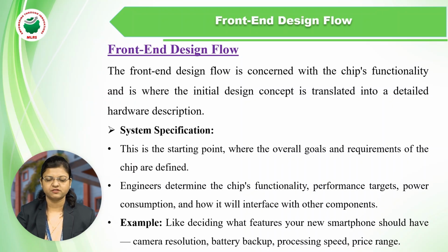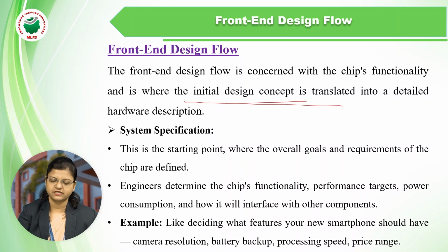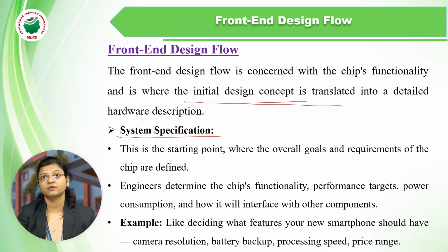So as we have discussed, the front end design flow deals with the functionality, and it is where the initial design concepts are translated into the detailed hardware description. So the front end deals with the hardware description language, from the specifications up to the gate level netlist. The first step involved is system specification, which is nothing but the requirements.